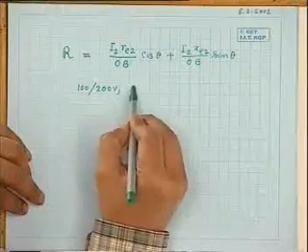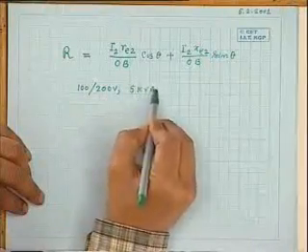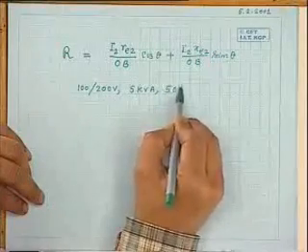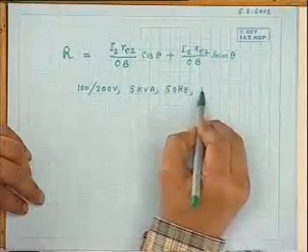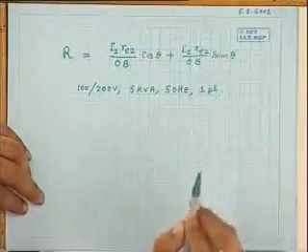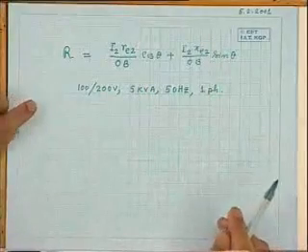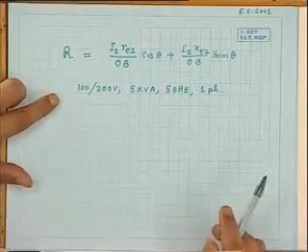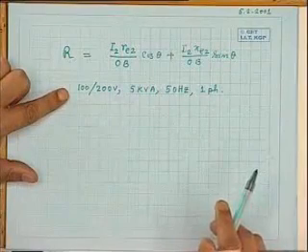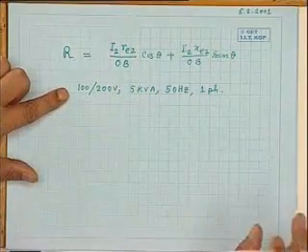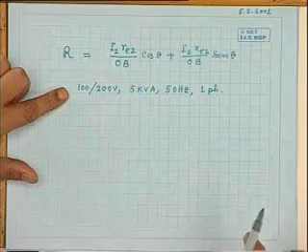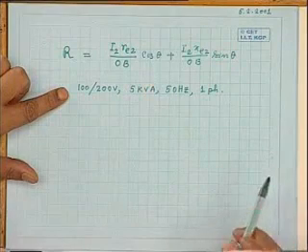Suppose, to give you an example, suppose you consider a transformer 100/200 volt, 5 kVA transformer, 50 hertz, single phase. Consider this transformer. You apply to the primary 100 volt rated. Secondary is open circuited. How much voltage will you be getting? 200 volt.